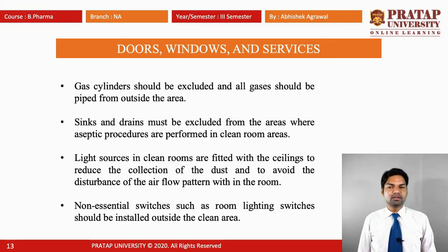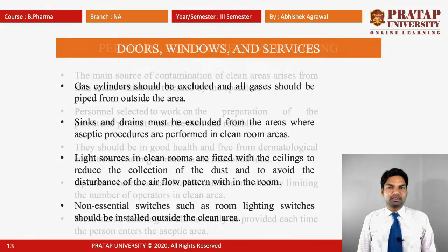The light sources in the room of the aseptic area are fitted within the ceilings to reduce the collection of dust and to avoid disturbance to the airflow pattern in the room. The non-essential switches such as room lighting switches should be installed outside the clean area.